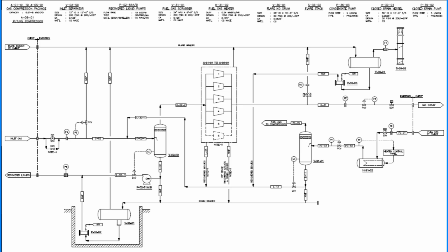In other words, a PFD is a diagram used to indicate the general flow of plant processes and equipment. The PFD displays the relationship between major equipment of a plant facility and does not show minor details such as piping details and designations. The symbols used in PFDs are generally based on the International Organization for Standardization ISO 10628:1997, referred to as flow diagrams for process plants, general rules.